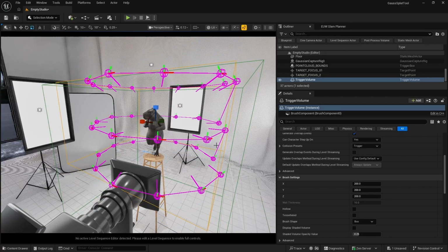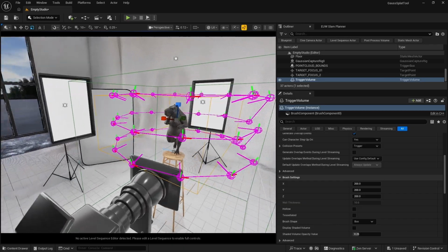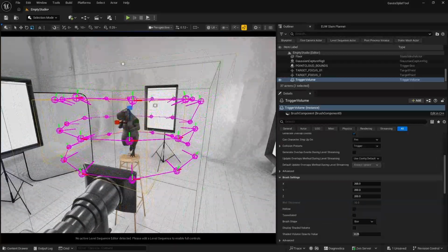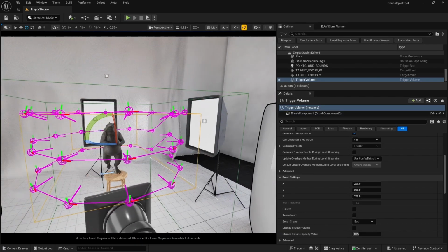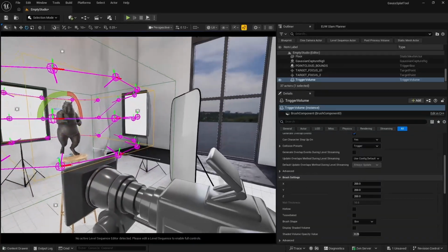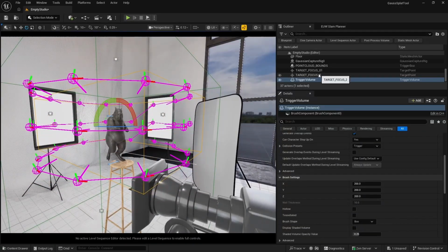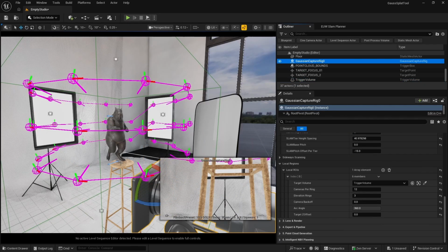Let's make that guy slightly smaller here. And then I can even do rotations if I want to, and you see it rotates the box. So the idea of the local regions of interest is to have the same setup but using local bounds. Maybe you want more detail on certain parts of your scene or certain objects. You can use these local regions of interest to define your paths and your cameras, and they have the same settings as the SLAM method.